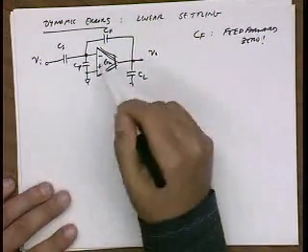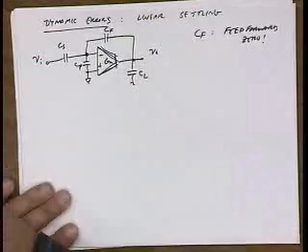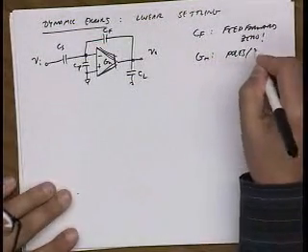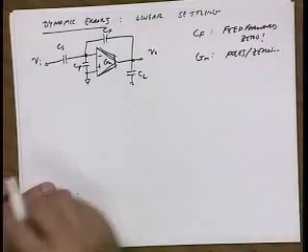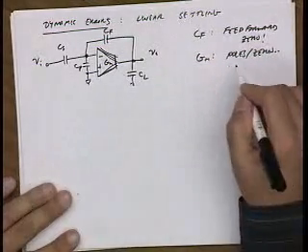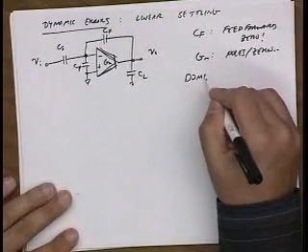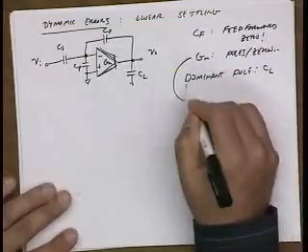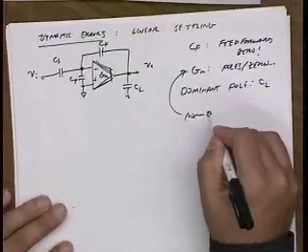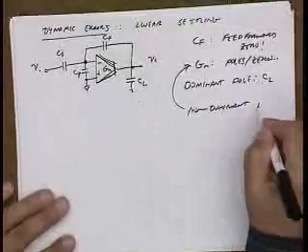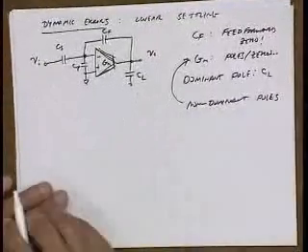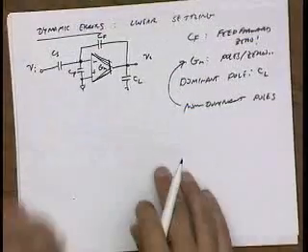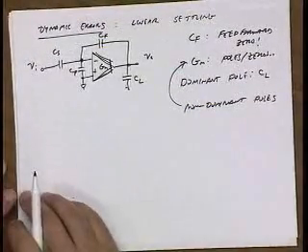So you go and build this transconductor, right? Obviously you're going to get a pole out of that. So the GM stage has its own poles and zeros. Okay? So basically we get a dominant pole from CL, and then these poles are what we call the non-dominant poles. These are the poles of the internal amplifier. That's why I said it's not a trick question. You guys all knew the answer.